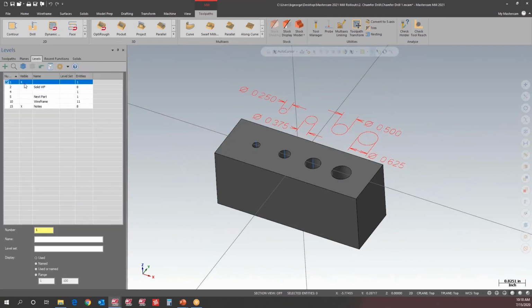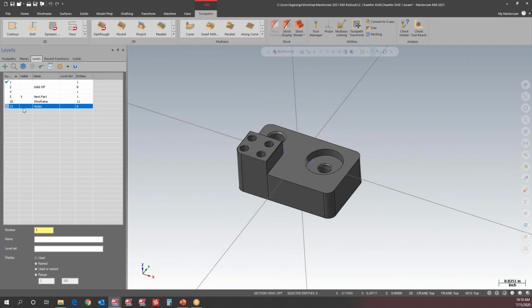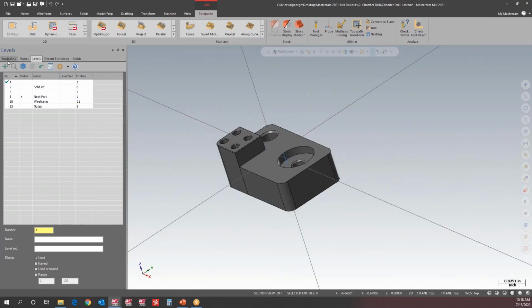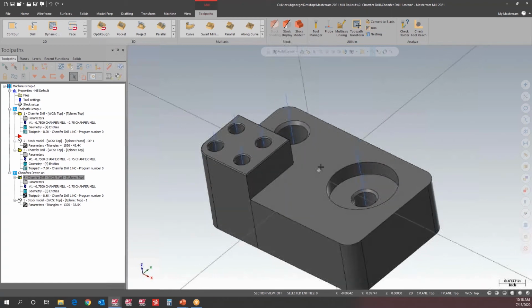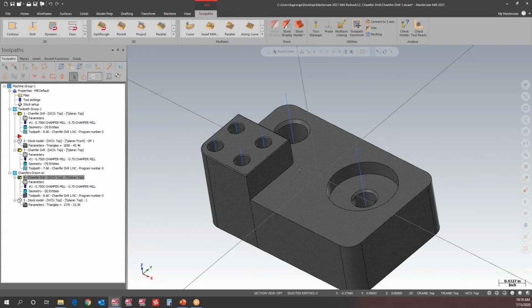Now, my other favorite part about this toolpath is that it can also do multiple depths on different levels. So let's take a look at something a little more complicated here. Not only do I have different Z depths for my holes, I also have different size chamfers. I think on this boss here, I've got 30 thou chamfers. On this floor here, I think that's a 50. And I think in here is a 40.